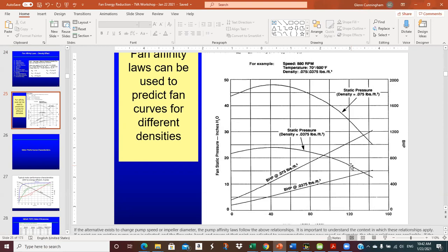Absolutely. You're doing a couple of things. One, we've been taking some oscilloscope measurements upstream of the drive. I've got a 15 horsepower fan and an ABB drive, about 6 or 7 years old. But there's significant electrical noise transmitted back onto your circuits by that drive. Now, if you got a new drive, it's probably better. But one, you're costing yourself 2-3% in additional energy, and you're putting additional electrical noise, harmonics, out on your power system.